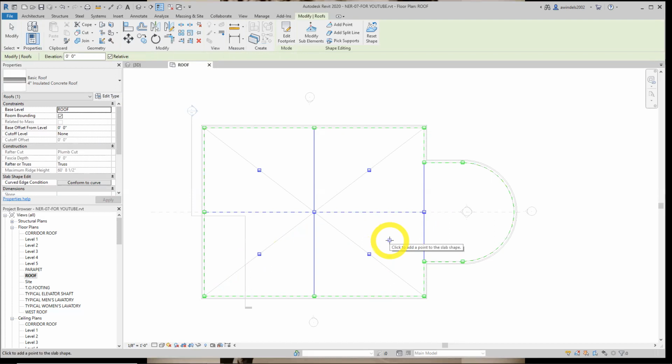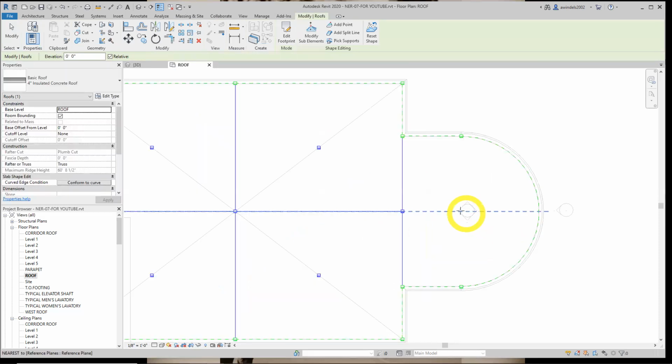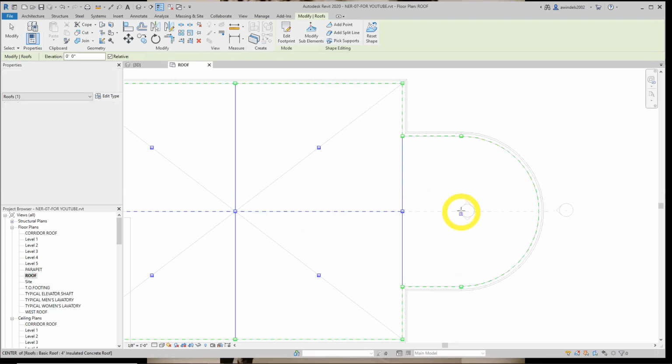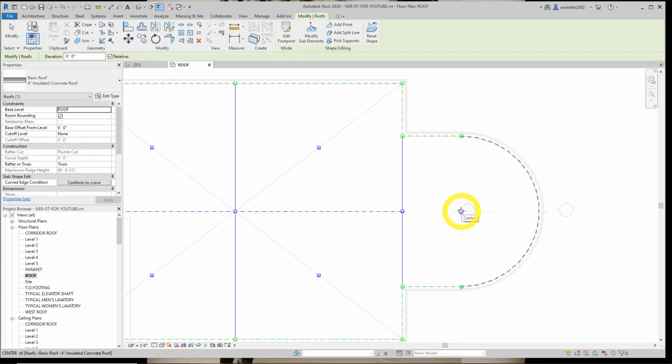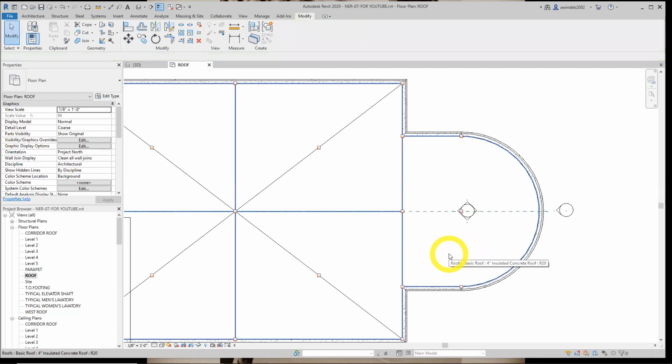And the last one, we're going to pick to the center of this, and it has to show a circle, which there it is, or you can type in SC, which will isolate the circle snap, or the center point of arc or circle snap, more accurately said. There we go on our last one. Step 7 on figure 11, I don't really understand the implications of it, so I'm going to skip that. Didn't seem to add anything to the benefit of this learning. On page 331, I'm going to exit out of here, hit escape twice.